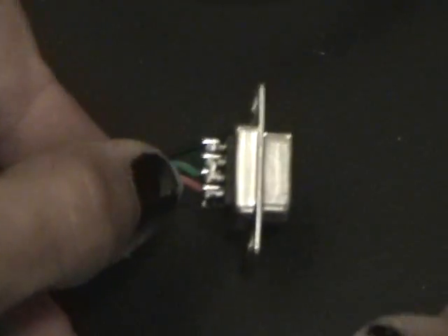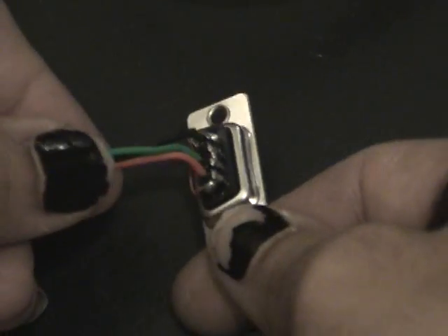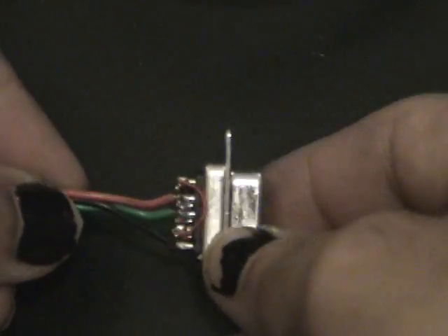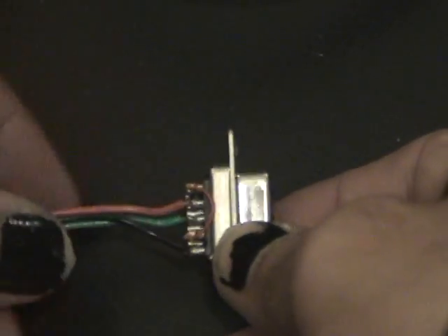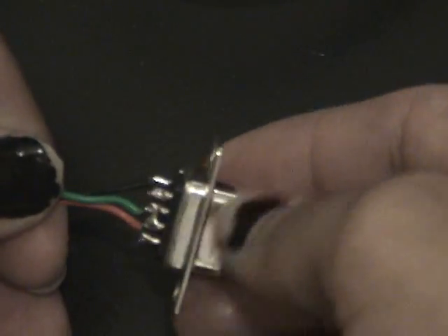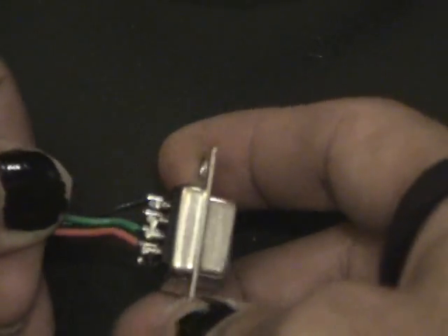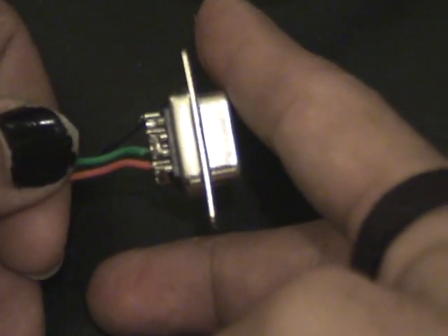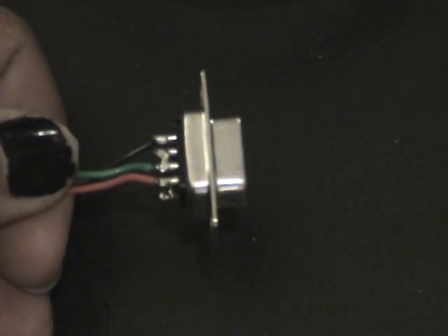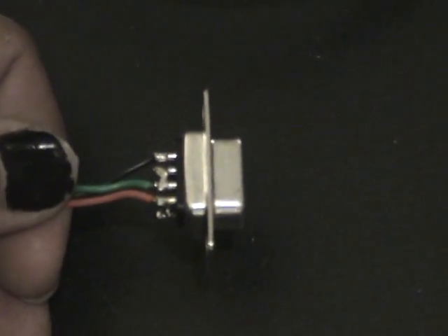As you noticed, with this actual header, I've actually jumpered a few pads. These pads are jumpered in a null modem configuration. If you notice that pin 1, pin 5, and I do believe pin 6 are all jumpered together, as well as pins 7 and 8. So these pins together will actually fool a standard typical PC into thinking that the machine or the computer on the other end is ready to receive and transmit data.